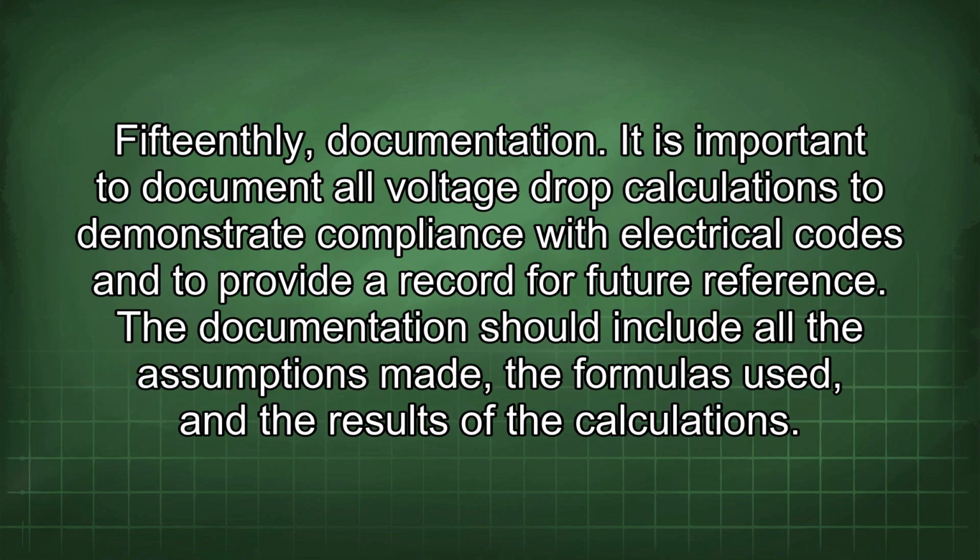15thly, documentation. It is important to document all voltage drop calculations to demonstrate compliance with electrical codes and to provide a record for future reference. The documentation should include all the assumptions made, the formulas used, and the results of the calculations.